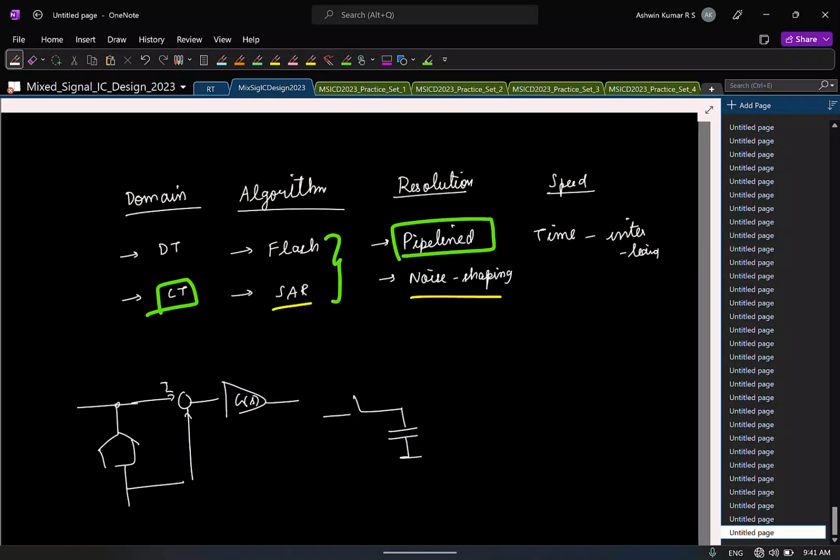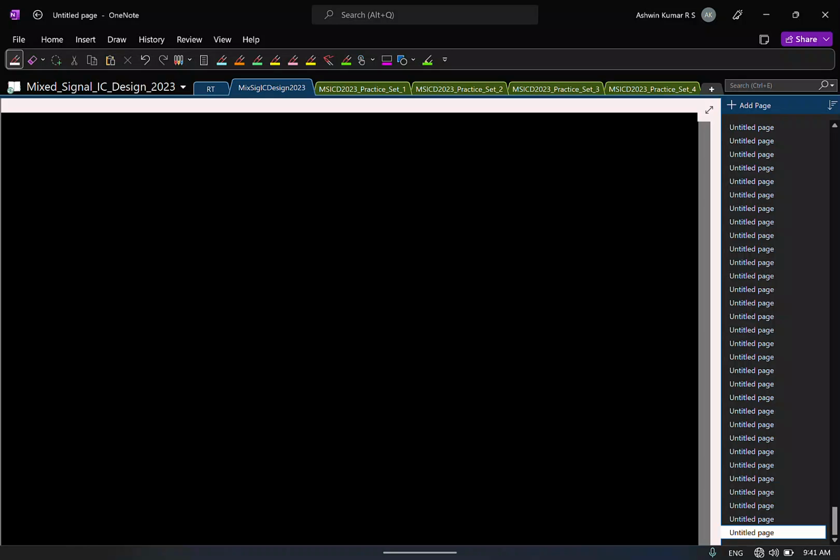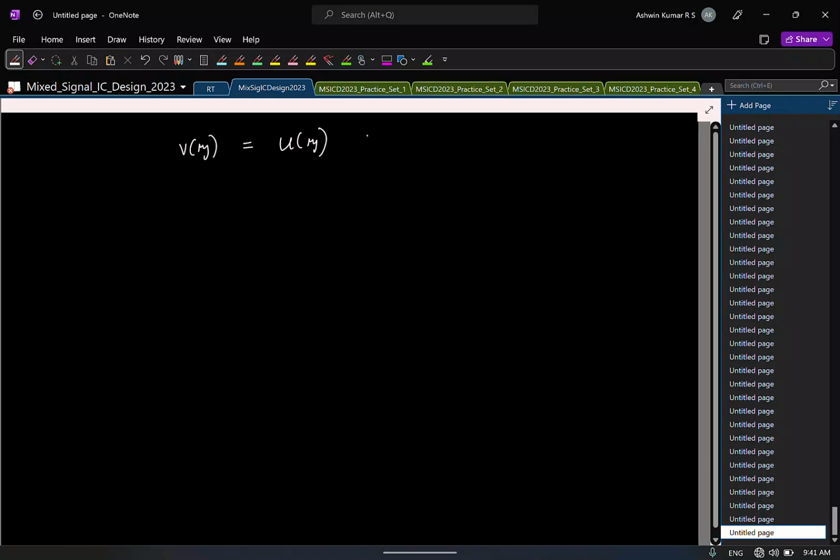Cool. So okay, one other thing I wanted to discuss briefly related to noise shaping. In noise shaping, all you want is this, right? Let us say in Z domain, my output must be the input, plus, if it is first order noise shaping, what do you want for the quantization noise? Q of Z times what for first order noise shaping? Times 1 minus Z inverse, right? And we sort of obtained this operation. This is what you want, and in circuits we implemented it in a couple of ways.